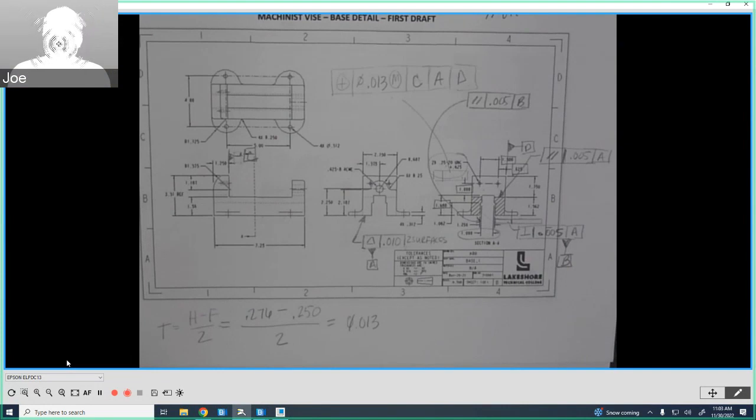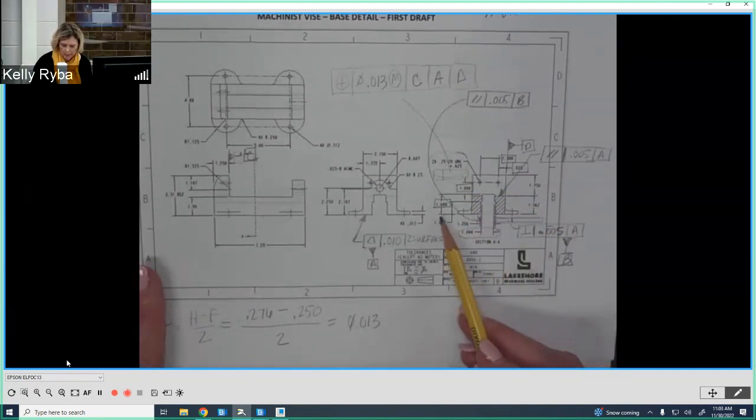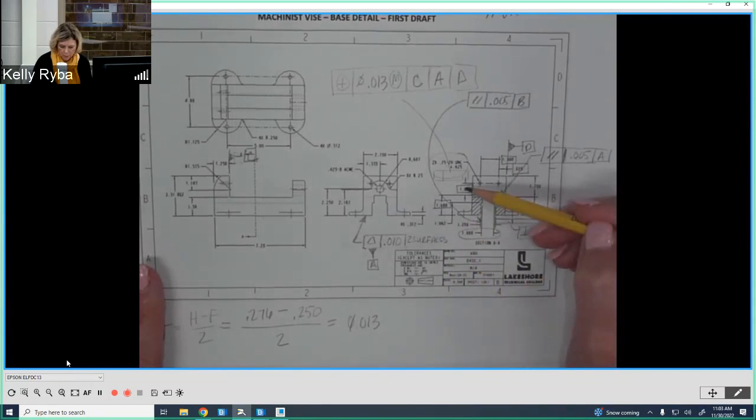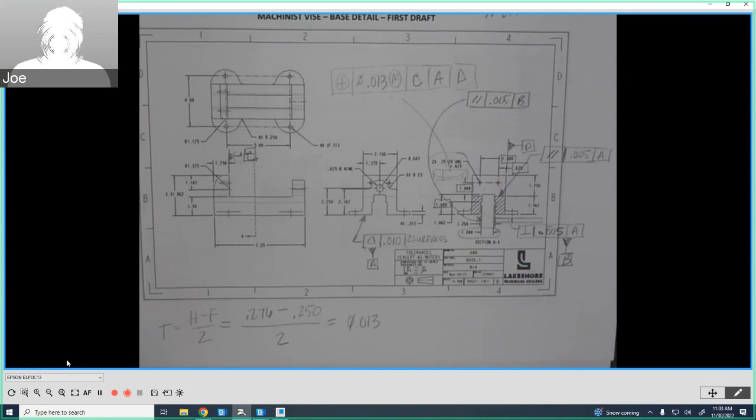And right now, that chains us, because we need to get back to the bottom here, right? And that's the one that's related from here to here. So those 2 have to be basic to get our position, our location for those 2 holes. Because we don't have a direct dimension right now. So do you know what I'm saying? Like that 1 inch dimension, I don't think it's dimensioned to the right place.